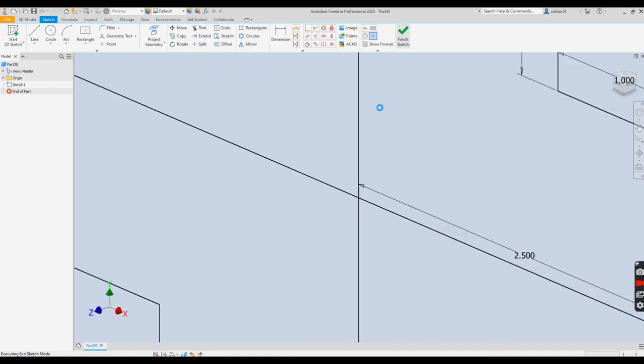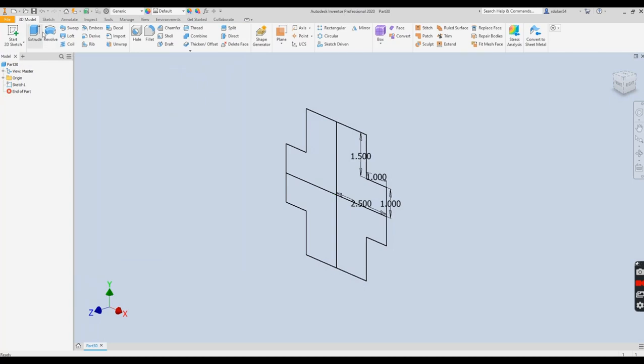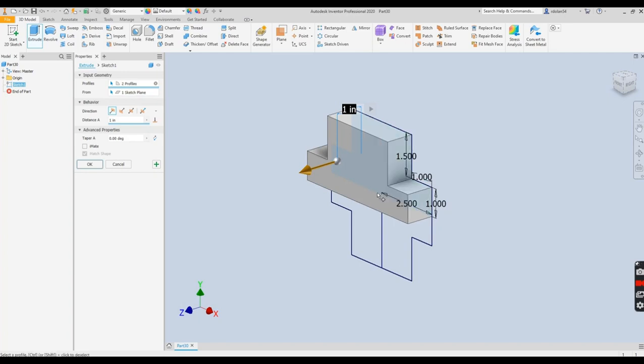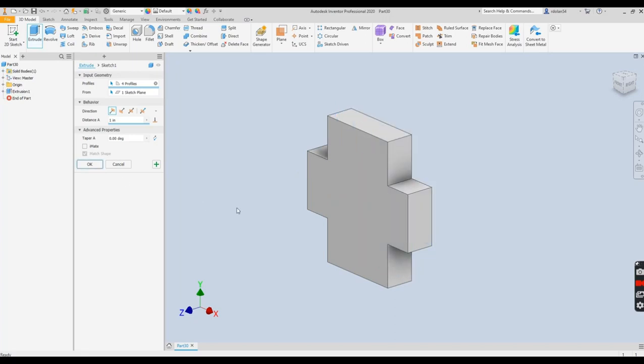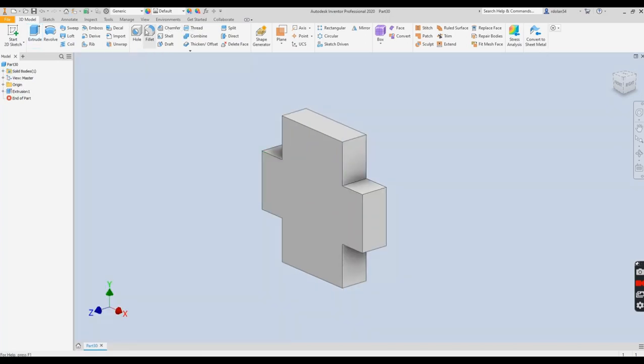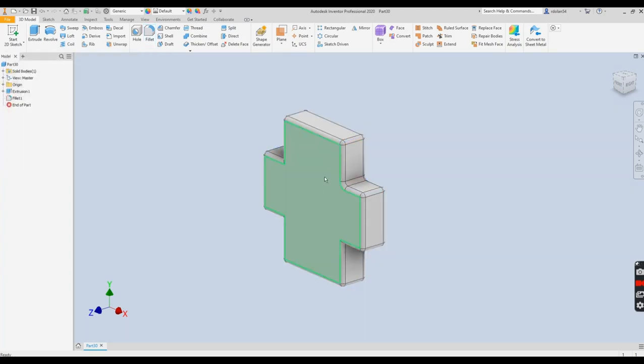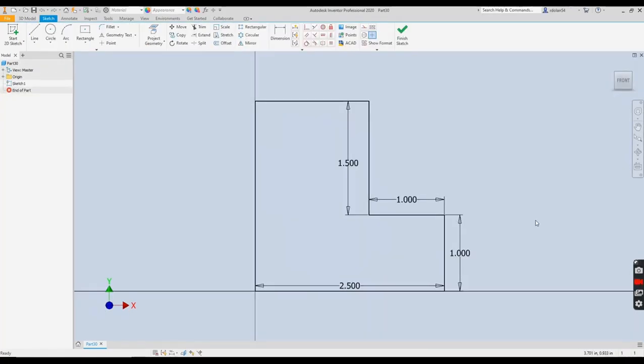and finish the sketch, and I could extrude that. Now you notice since I left those center lines here, I have to pick each one separately, but it will make it one object when I'm done, and I can pick OK. We looked at this before, and I could put fillets on this guy, put some there, or I can put all fillets in rounds. So there we have our mirror command. Back to my original sketch here, and I'm going to take a look at rotating geometry.